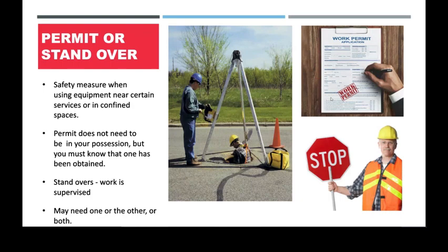In some cases, they'll actually use a hydro truck. So it's basically a water blasting truck with a vacuum on it, and it blasts all the dirt and gravel out, and then it sucks all that out to expose the services without you actually having to get in there so much. That's sort of big scale stuff, roading type stuff, but it's all part of drain laying. Also have a plan in place, so if something does go wrong, everyone knows what they're going to do.